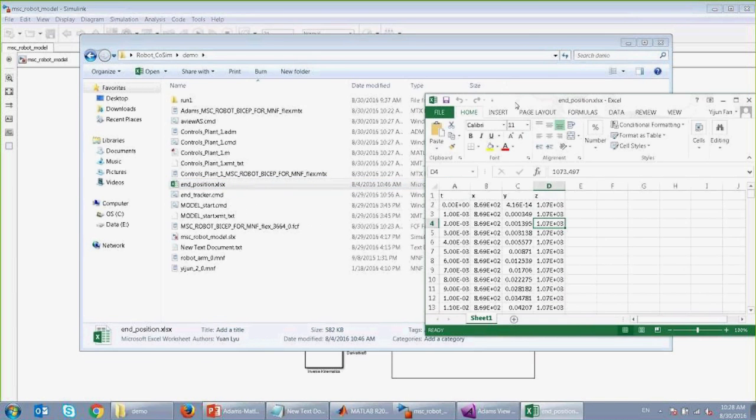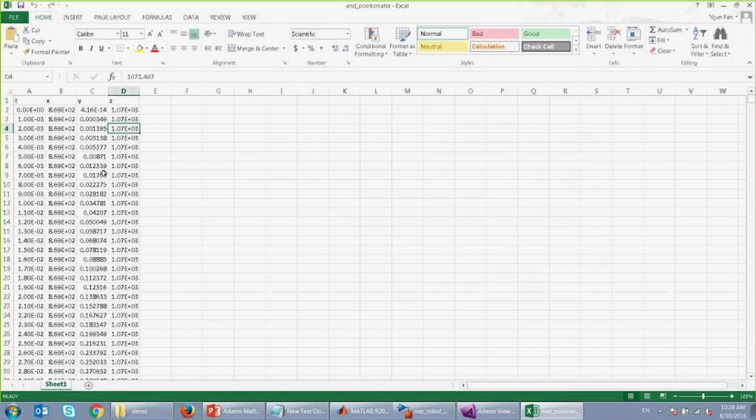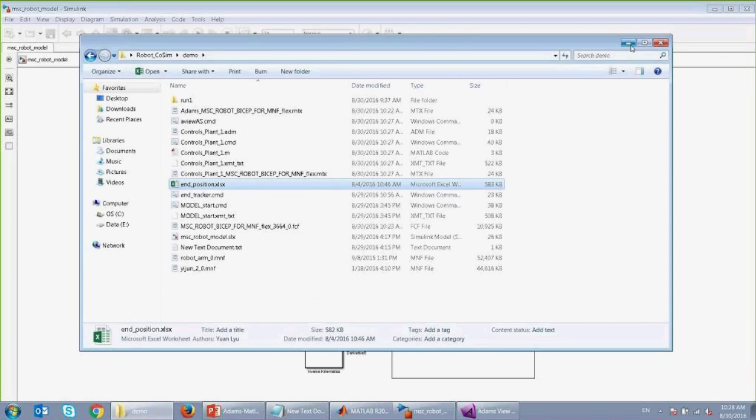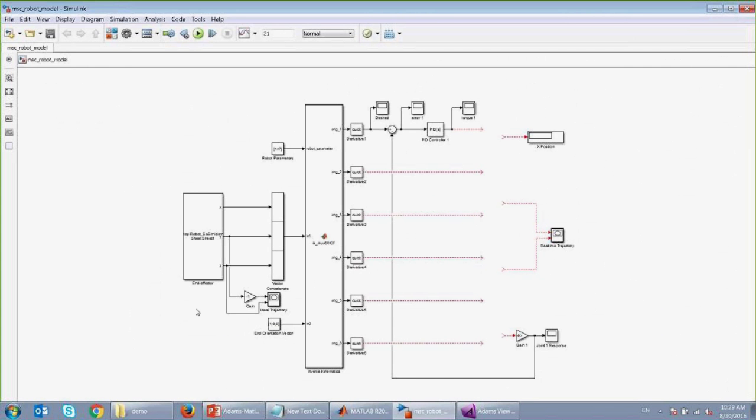In that file, you will see the trajectory of basically the XYZ position of your end effector that you want it to go through. So how do you translate that into the angular velocity or the torque that you need to control each joint? There is a paper that shows you how to do that. It's called inverse kinematics. I believe a lot of you have heard of that.